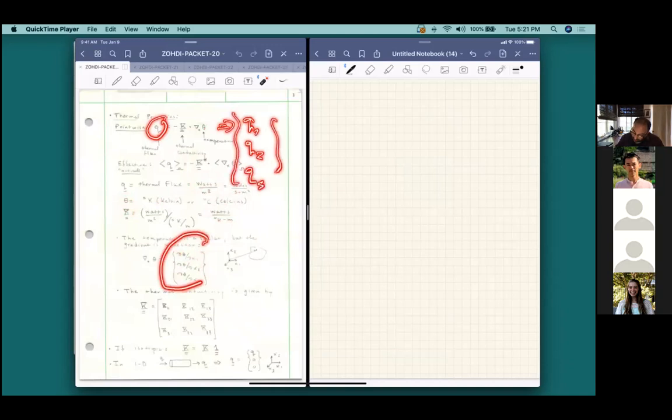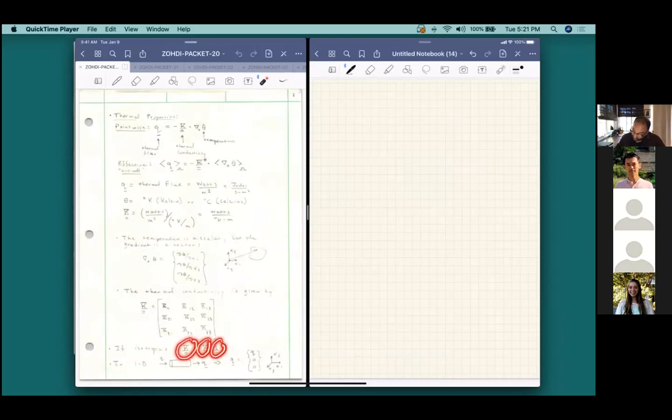The thermal field, or the gradient of it, is also a vector. So what relates the two vectors to each other is a matrix of constants, and we refer to that matrix of constants as the thermal conductivity. In the special case when the thermal conductivity is a scalar, we can write it as K times I, and therefore we get the simple relationship that Q is equal to minus K times the gradient of the temperature. And of course, this is the number we usually refer to as the conductivity, or the thermal conductivity, of the material.